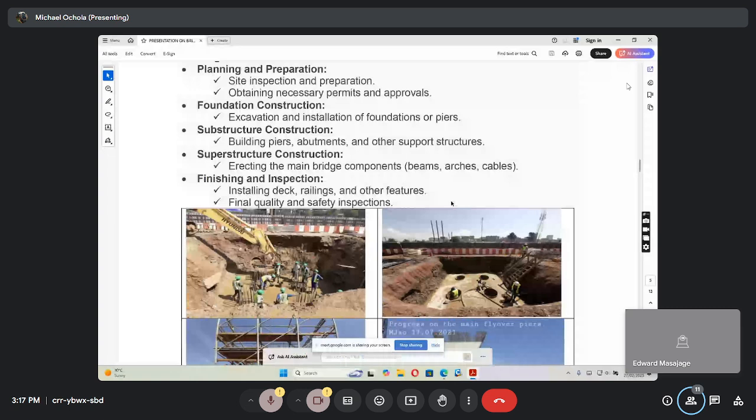First of all, I want you to check this again. This is not good practice. These people are down here, almost 3 meters below the excavation, and they have supported the site. If it is recklessly handled, it can collapse and people die. Now you look at the safety aspect. When you are doing excavation, what happens? As a project manager, in the meeting you make sure your site engineer is on top of his game. The site engineer looks at the site foreman, and the site foreman looks at the site technicians and inspectors. All these things must be designed for, and checked on a regular basis.